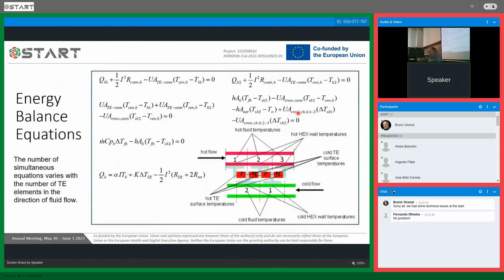Okay, one of the main things that I have done in my work in thermoelectrics has ended up being in modeling and simulations. So I show this initial slide just to show, again, here's our T-shaped design, but I was looking to be able to simulate how this would perform. In whatever material, I had to have temperature-dependent properties of the thermoelectric material. That can be shown here, where you have alpha for the Seebeck coefficient, kappa, which includes the thermal conductivity, and the electrical resistivity is in the R, and you still have interfacial resistance here.